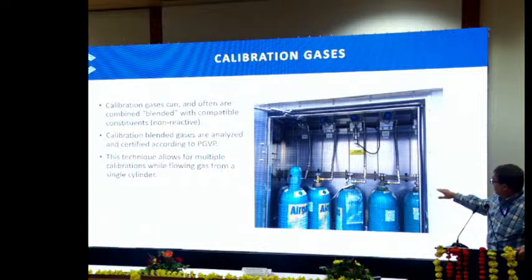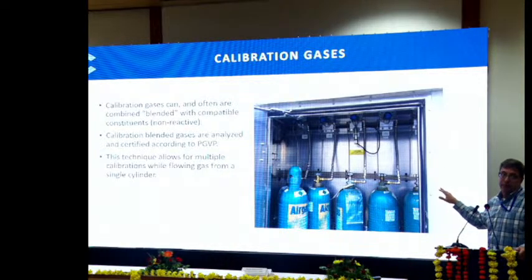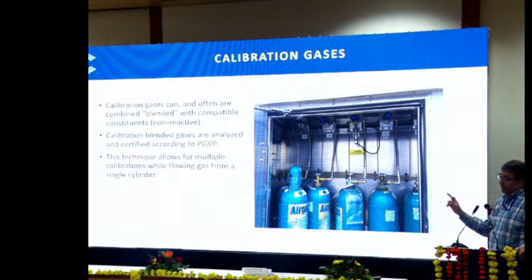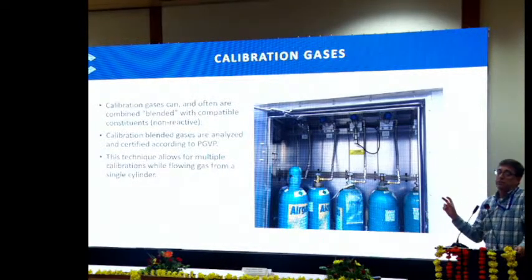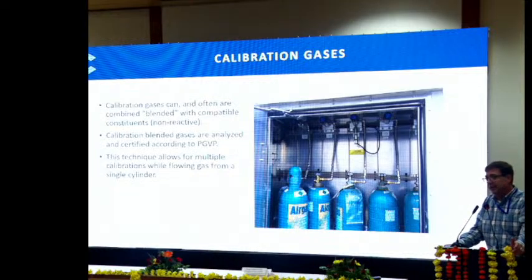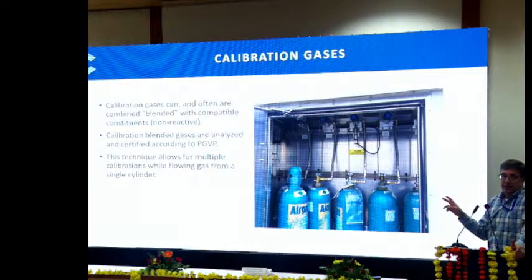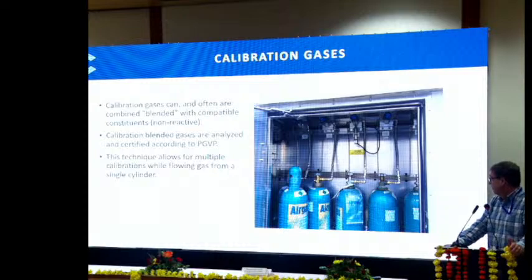You can kind of see in this picture, this is only half of one shelter that we have. The regulators are mounted up top. On top of those regulators, we have pressure sensors, so we can monitor the pressure in the cylinders. If one starts to run low, we know when it's running low. An alarm is triggered in our data logger, our data acquisition system. It will send an alarm to the control room, and they will know when they need to change out a cylinder, for example.